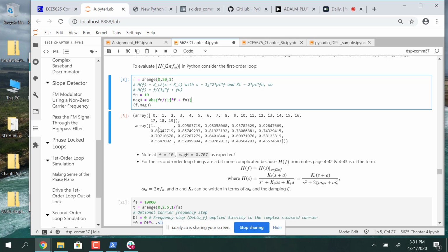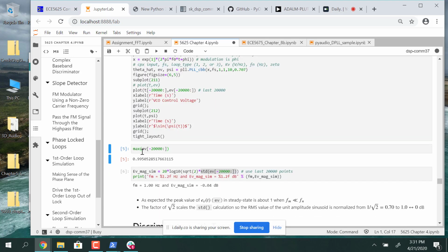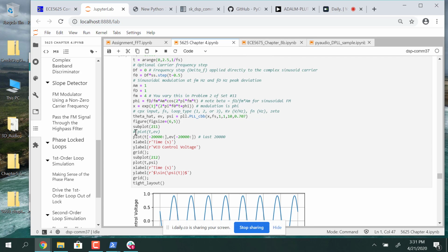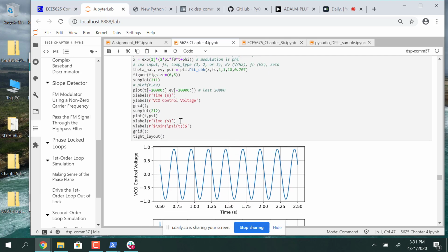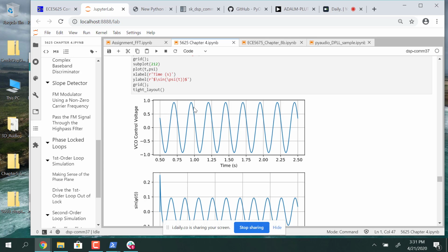This would be at 4 Hertz, right? So 0, 1, 2, 3, 4. So at 4 hertz, my sinusoid should start to decay a little bit. So let's put in 4 hertz and see if I get around 0.92. So I'll change FM over here to 4. And I can see what my amplitude is right here. And it's 0.9289. So it's pretty much what I was expecting it to be. I've got 2 plots. I've got the phasor, but it's the upper plot that we're looking at. So we're seeing it starting to shrink.